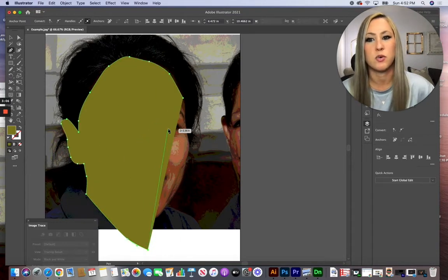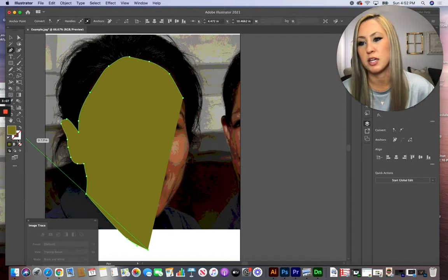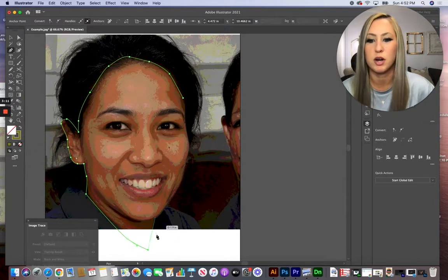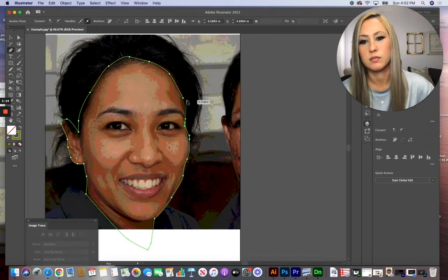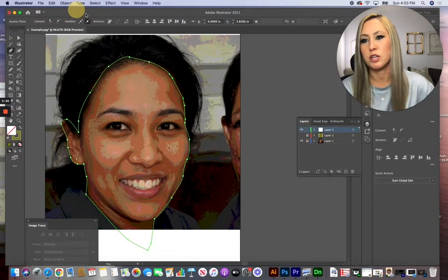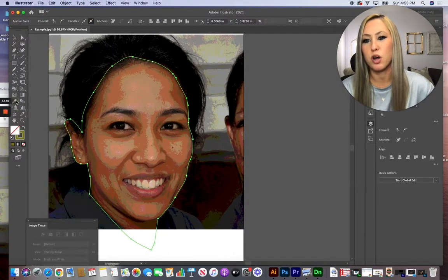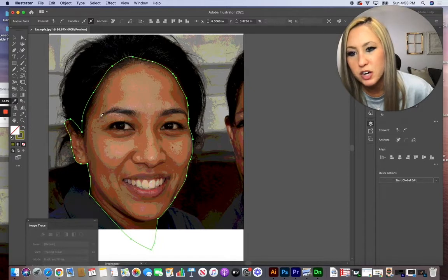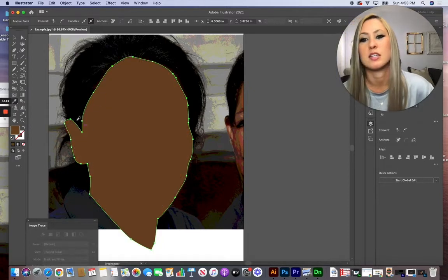Now in Illustrator, it's going to start to fill it automatically. I can either turn that fill off or switch it to a stroke by using the little arrow that's right above it, so I can actually see what I'm doing to draw. And once I have that basic shape created, using my eyedropper tool in either program, I can grab an actual color from the image, so whatever the most background color is going to be. So one of my shadow values first, I'll start with that one on the outside as my base color.